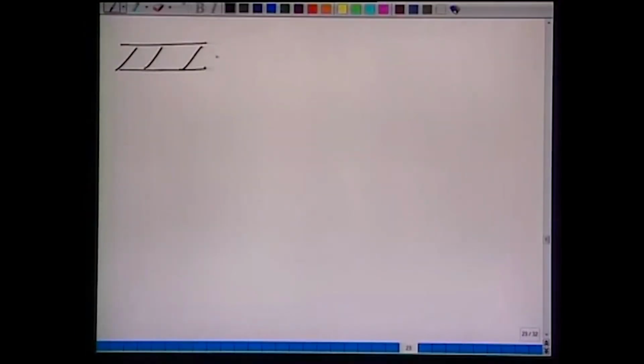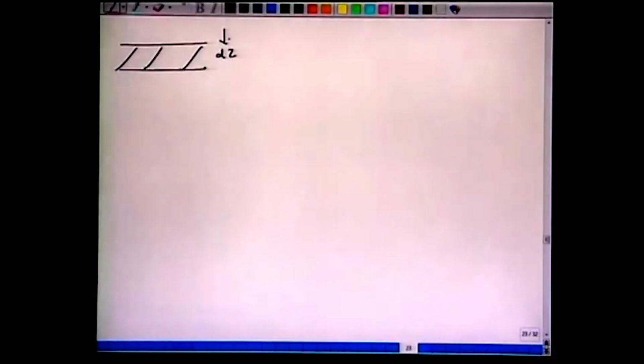So, across this differential element of dz, we have gas flowing like this and the liquid flowing like this, L and G. If you make a species balance over this differential, you have d(Gy), the change in the gas phase concentrations, d(Gy).